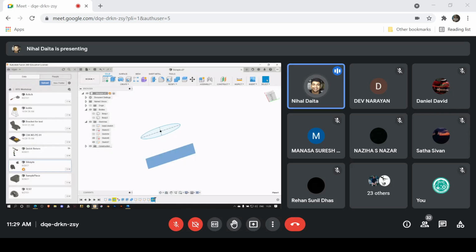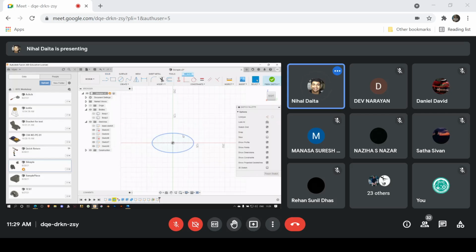So you click on this plane and I click on sketch, right? As you can see, where I'm drawing, it's an entirely different plane. If I click enter, as you can see here, this was the earlier preset plane. The current drawing lies on another plane entirely. Let me just undo that.